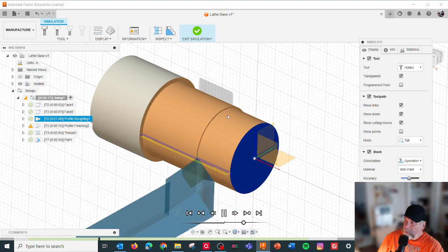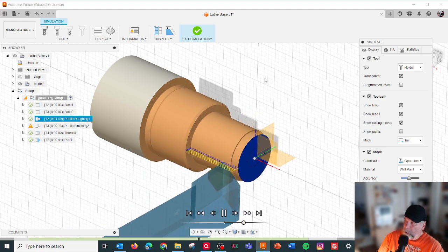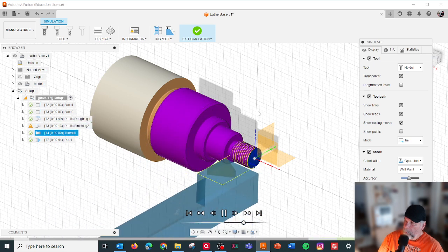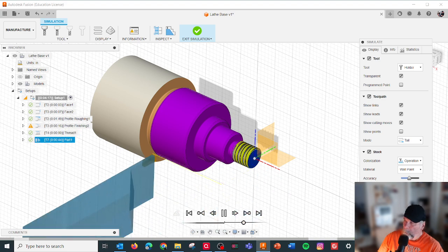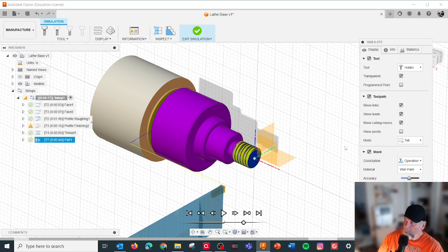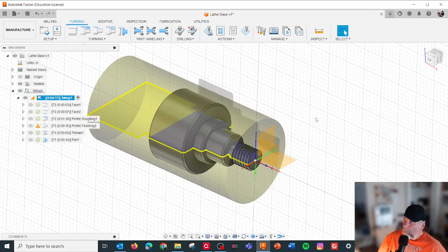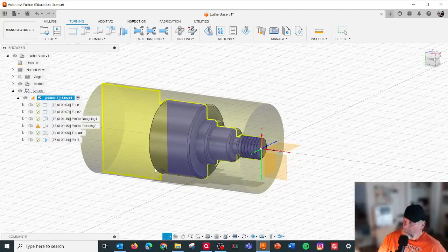Now in lathe, I prefer the lathe tool to be coming down straight. So everything looks good. He's also got, I got stop on collision on, so it'll give me a warning. Let me bail out of this. Exit. Let's see, why is it, I got Z up, oh, X is the index. So X is facing this way, so usually I got X facing like that.